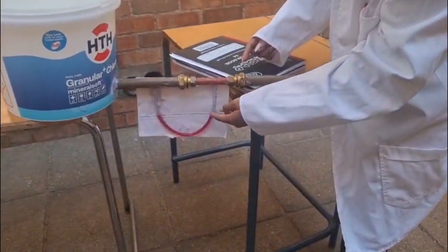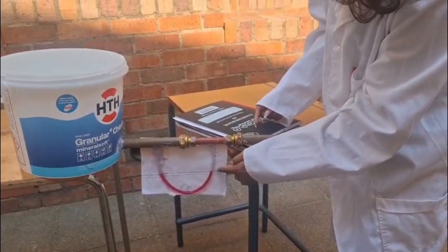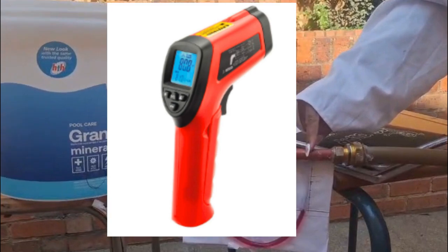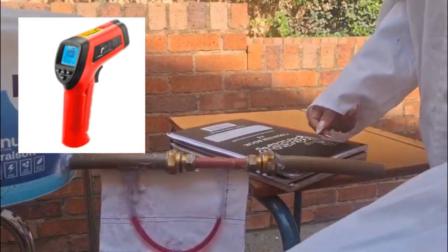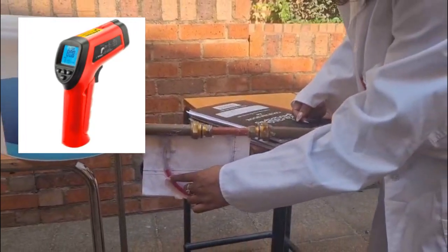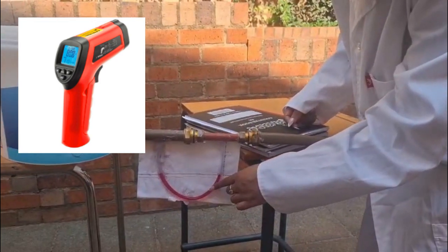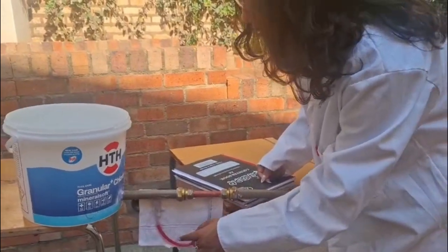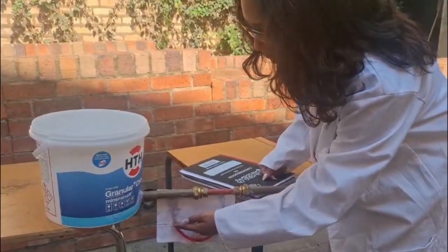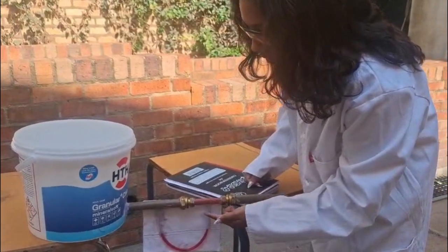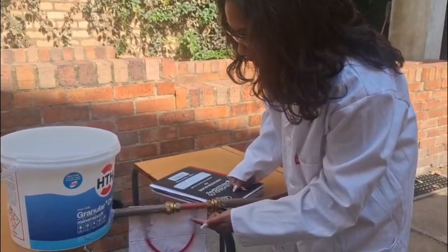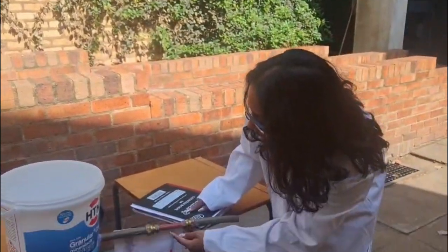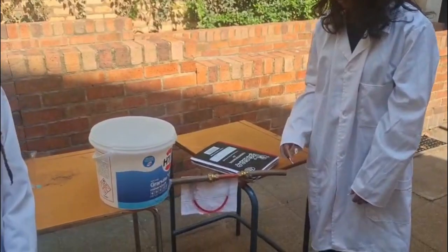The height difference observed in the manometer reading represents the pressure difference between the static pressure at point 1 and the stagnation pressure at point 2. A surface thermometer was used to measure the temperature of the water, as temperature directly influences the density of water and consequently the accuracy of the results. A bent plastic straw was inserted facing the oncoming flow at point 2 to measure the stagnation pressure. Since point 1 serves as the static tap and point 2 as the stagnation tap, the setup effectively functions as a pitot-static tube, allowing for the determination of flow velocity based on the pressure difference between the 2 points.